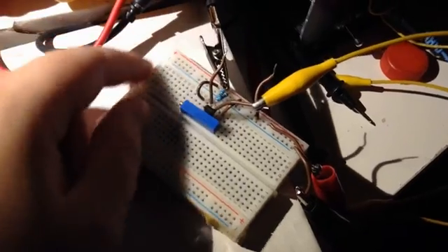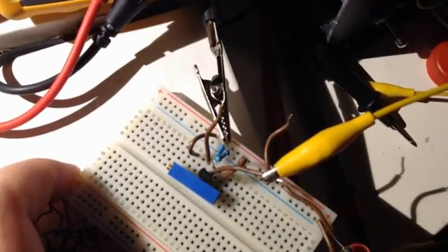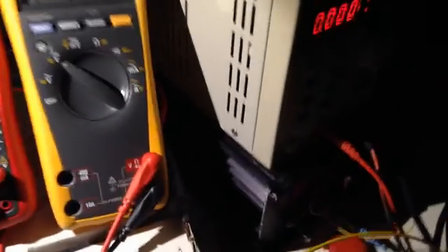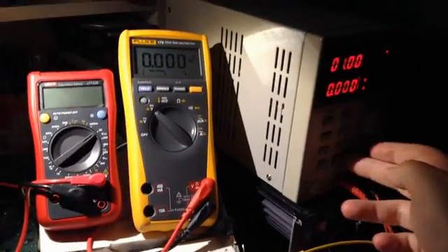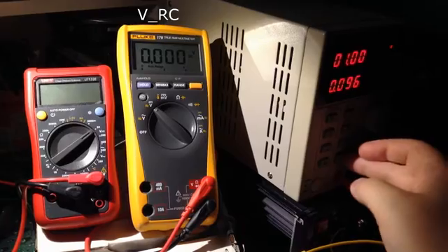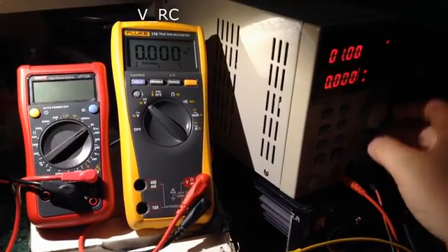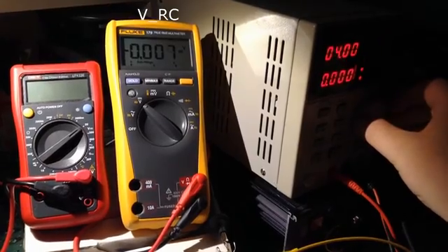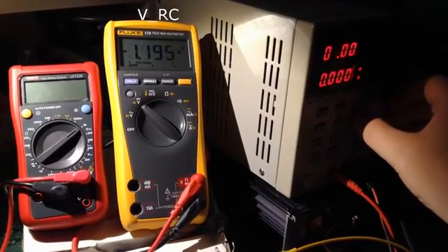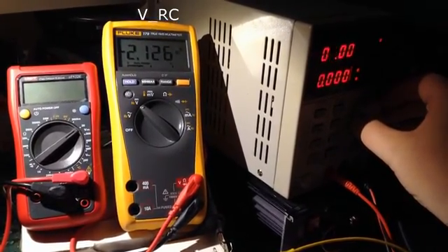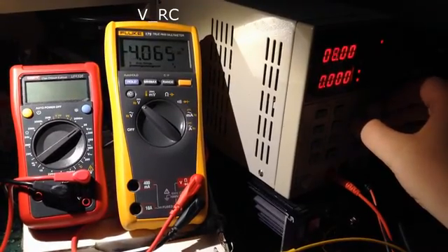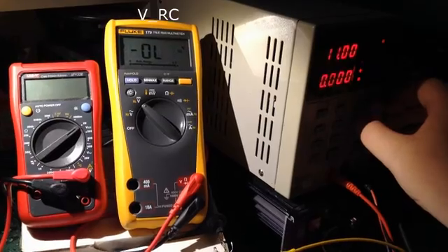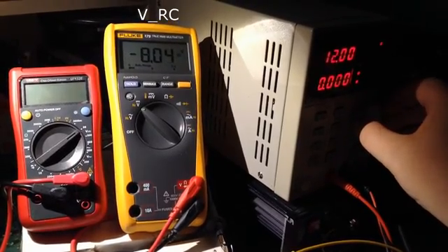So you may wonder what's the point of all these resistors in the circuit. Well, the transistor alone is not very linear, it's very nonlinear, logarithmic. So by using resistors you tame it, and also from transistor to transistor this gain can vary as much as 100 times. But with these resistors none of that really matters. What matters is that the gain is high.